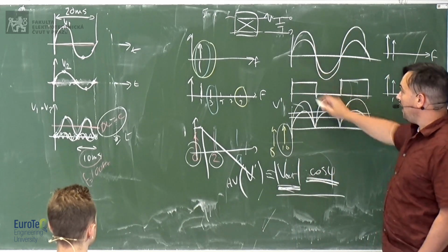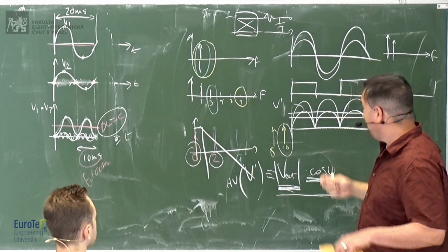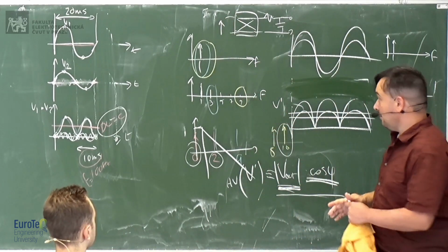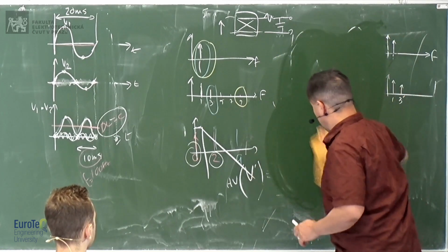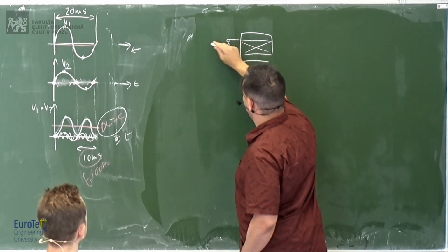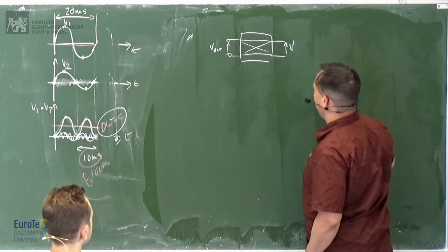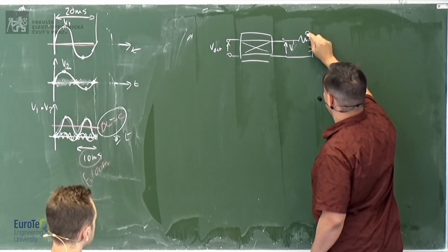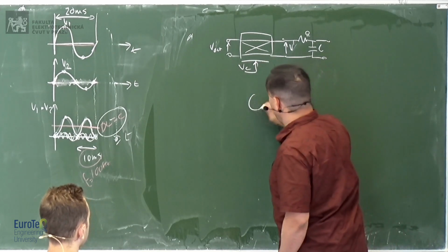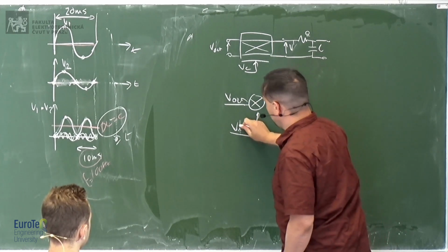So the ideal would be to multiply times a sine, okay? The best thing to do is not to use this polarity switcher. Theoretically, the best would be to take your voltage here and multiply it times a sine wave, okay? So if you are very rich, what you can do, instead of having your polarity switcher, so this is the output voltage of your operational amplifier. This is V prime, and then we have the low pass filter. Instead of using this circuit, and this is the control voltage, you can take V out and multiply it times V1, the input voltage of the operational amplifier, okay?